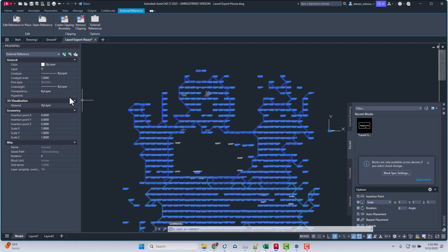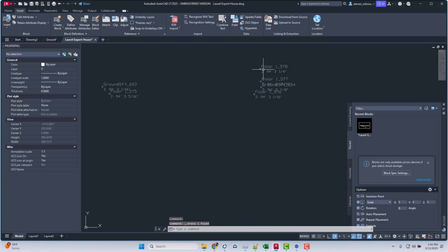I'm going to delete this one just to show here's my patio. Some new ones, I'd probably want to name those better so I knew what they're measuring to. But obviously, here's my table at 97 and 2 inches, whereas the ground patio is 94 and 7 inches. So I can bring those in.